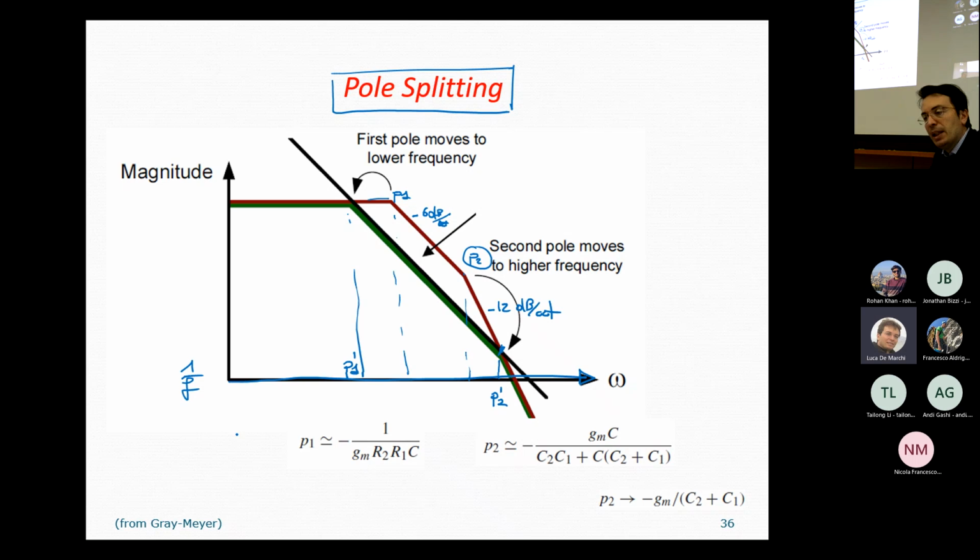For the single stage amplifier, you may remember that the load is placed at this node here, and when we apply a complete unbalancing, so when we apply a step function either to the negative input or to the positive one, then all the current generated by transistor number 5 flows into the load capacitance.